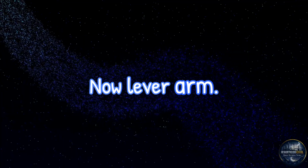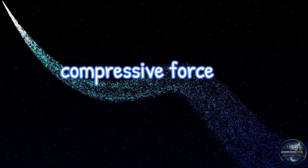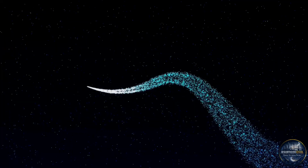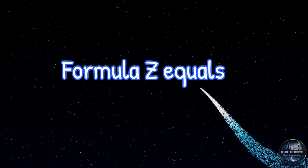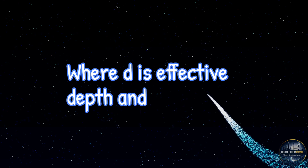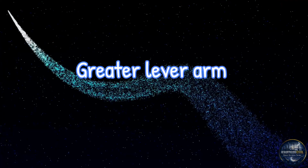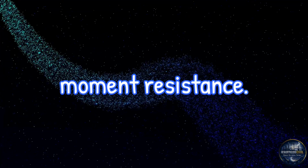Now lever arm. Lever arm is the distance between compressive force and tensile force. Formula: z equals d minus x by 3, where d is effective depth and x is depth of neutral axis. Greater lever arm means higher moment resistance.